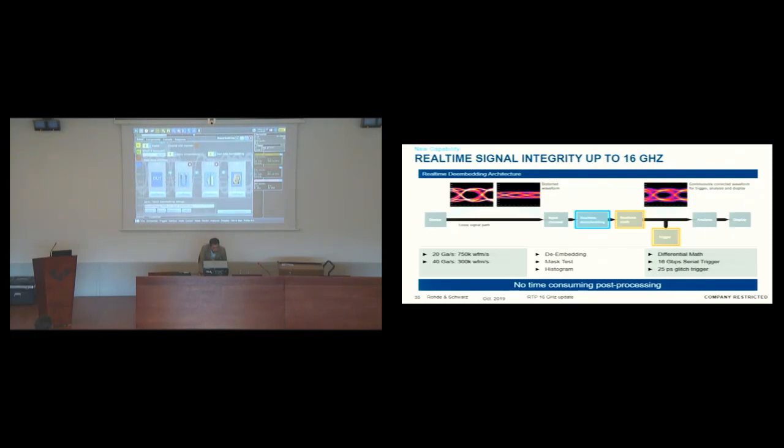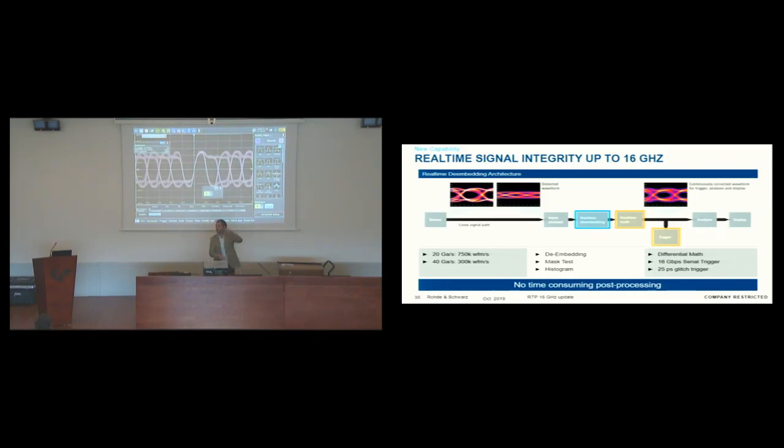So now I disable the de-embedding. And now, maybe it's better to get the statistics. The mean is more or less 800 millivolts, and when we apply the de-embedding, now it's 840 millivolts, so it's 40 millivolts bigger. So now we are really growing the eye.